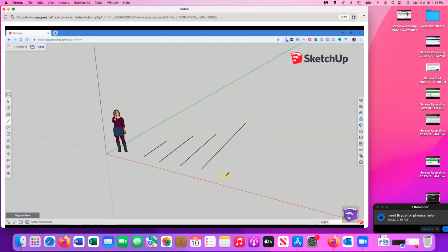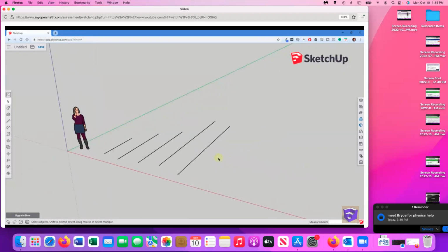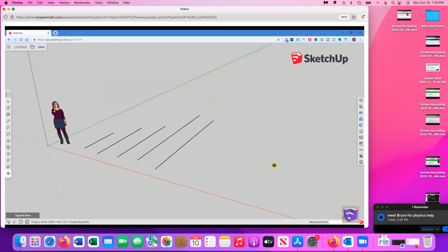But on the other hand, if you activate the line tool by tapping the L key, you single click, and then you move your mouse in this direction, note that now I can type in a value of 15-foot 4 inches and hit the enter key. So as long as you don't click and drag, you can type in values for the dimension that you want your tool to draw things in.